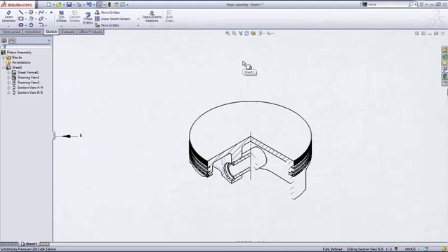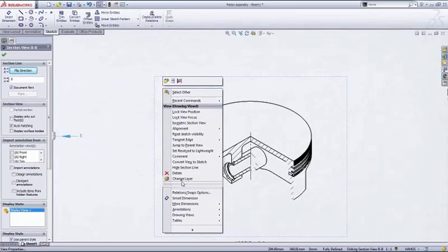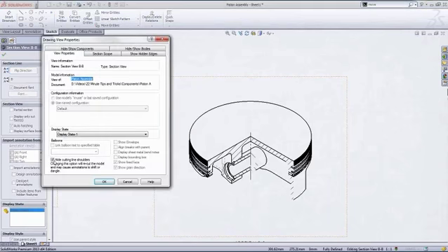Now, the line work in this view doesn't look that good, and this is the second part of this trick to make these look nice. We want to go into View Properties and set the option Hide Cutting Line Shoulders.